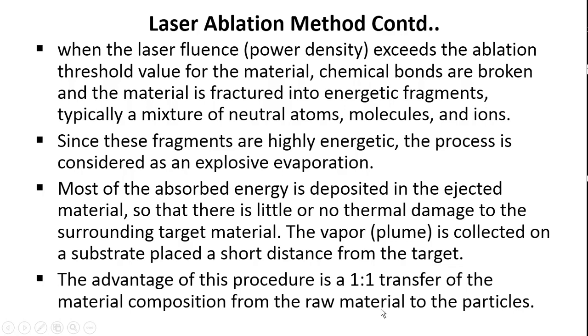Whatever the raw material is, whose nanoparticle has to be produced, whatever energy in the form of laser beam we apply on the target, the amount of energy absorbed by the target material is transferred to the ejected material, which will be available in the form of plume, the vapor of the material.